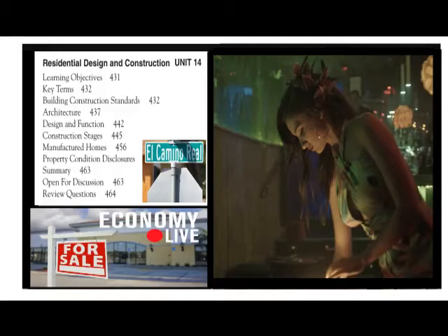A. Make a clear distinction between above-grade finished square footage and below-grade finished square footage and identify a level as below grade if any part of that level is below the grade line. A. Not include openings in floors in square footage but do include stair treads. A. Include accessory apartments and other finished areas not within the main house only if they are connected to the main house by finished hallways/stairways. A. Never consider a garage as finished space, although a garage can be calculated as unfinished square footage.